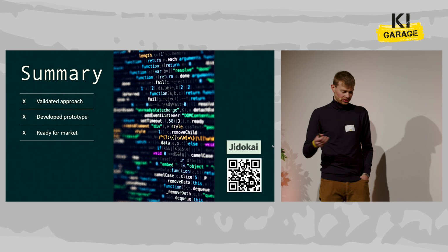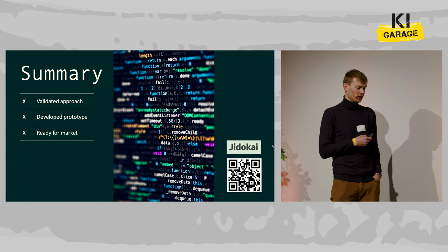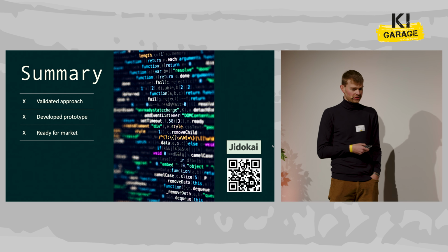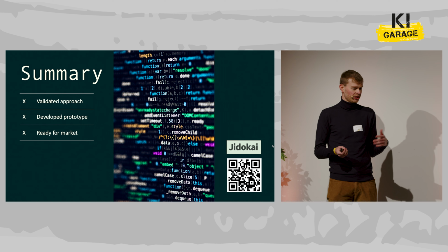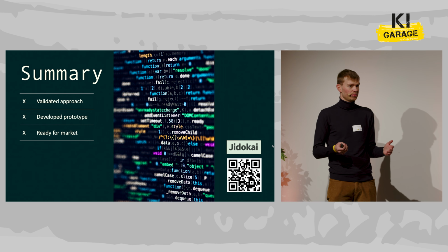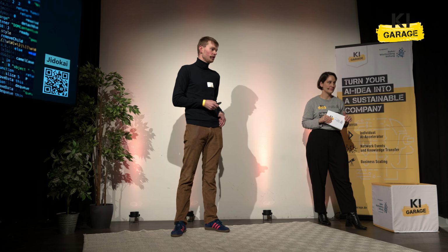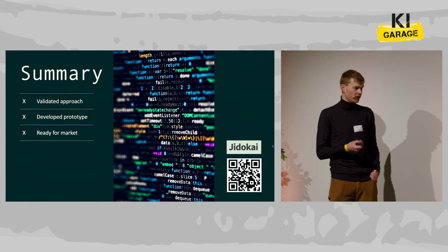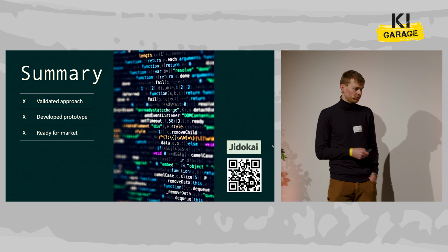The good thing is I just need to measure the electrical current. The others measure a lot of stuff like vibration and so on, but this is a lot of effort if you want to do it for a lot of machines. And the electrical current is there for every motor. So you just have to put the software on it and you have the monitoring of several faults. It's not just mechanical, it's mechanical and electrical faults. So you have everything in one place.